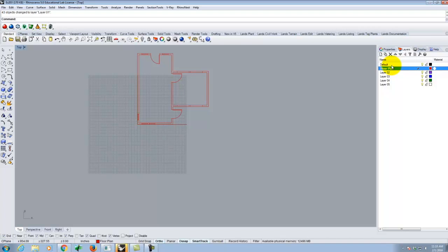The one other thing that I will point out in the world of Rhino that is different from AutoCAD, and I think the reason that I compare this a lot to AutoCAD is because a lot of people have familiarity with AutoCAD. If you've never worked in AutoCAD, my comparisons don't mean anything to you, but for those of you that have worked in AutoCAD, sometimes the comparison is the easiest way of explaining it. The one thing that Rhino has that AutoCAD doesn't have is it can nest layers. And it kind of works like grouping layers in AutoCAD, but it's not as intuitive.